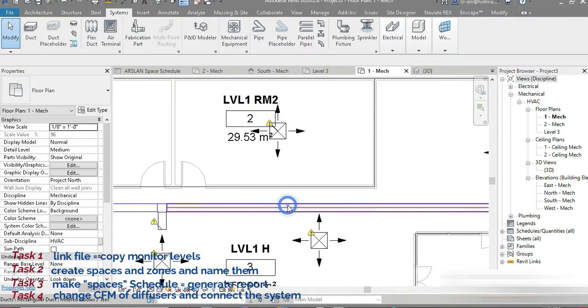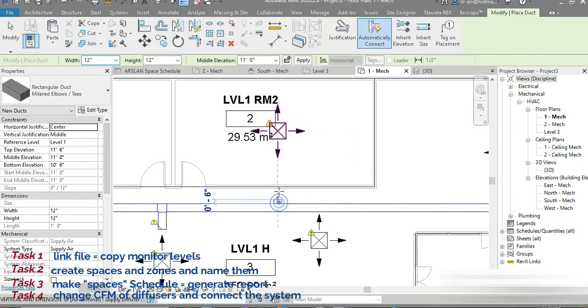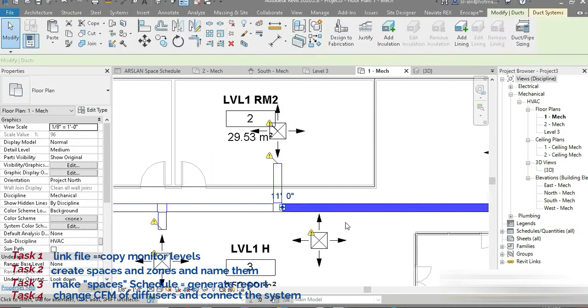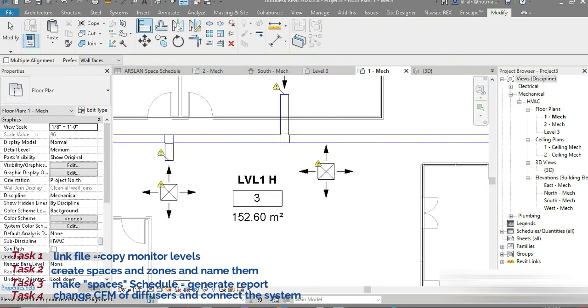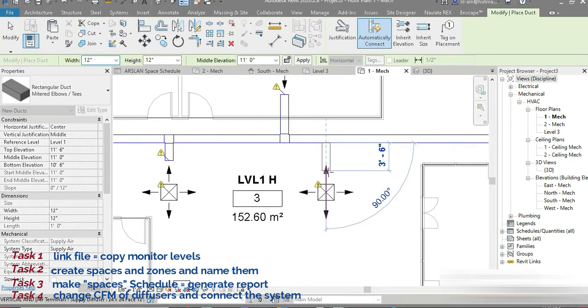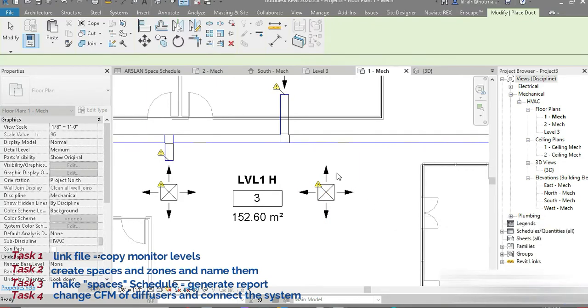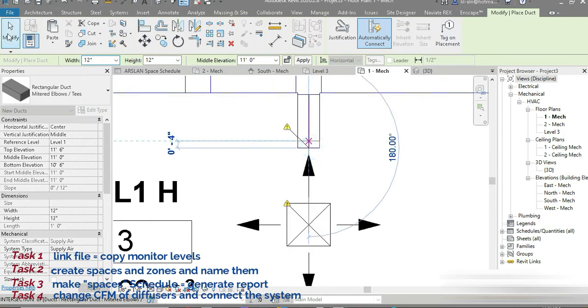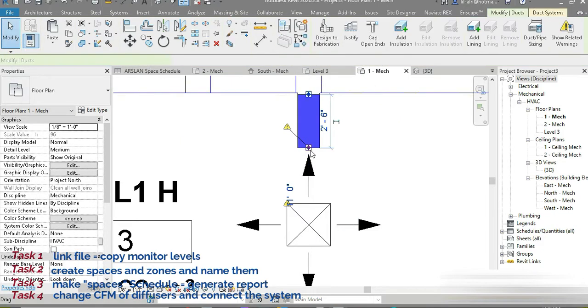After that, let's click on this point right here, CS, which is again create similar, and make it until this point. Click on this point right here and press AL, which is align, and click on this and click on this. Perfect. Click on this, click on that, CS, which is create similar. You do not have to touch these arrows because they are going to give us a small error right here.